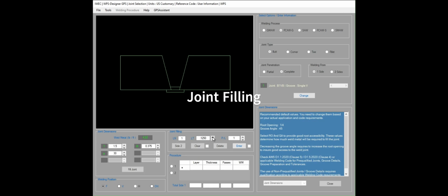Control of root pass thickness will avoid centerline cracking and slag inclusions and will ensure adequate fusion and penetration. Control of fill pass thickness after root pass will ensure adequate fusion. Maximum single pass layer width is required to ensure complete fusion throughout the cross-section of the weld and freedom from slag inclusion.